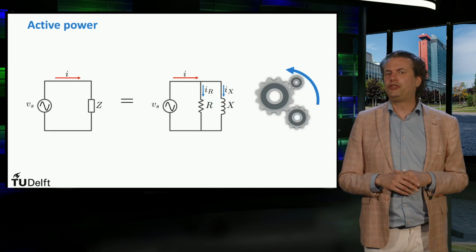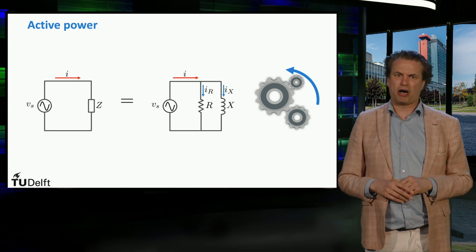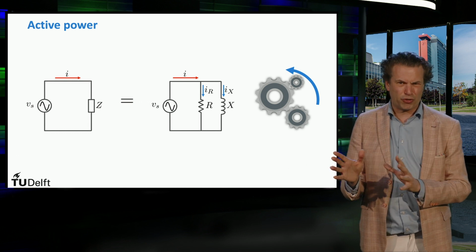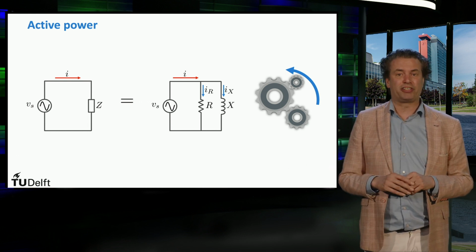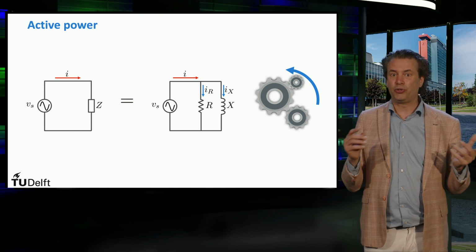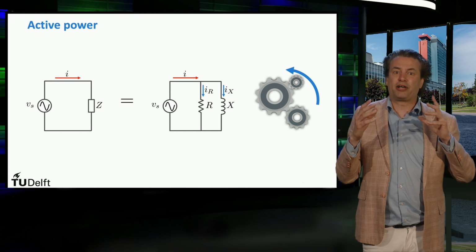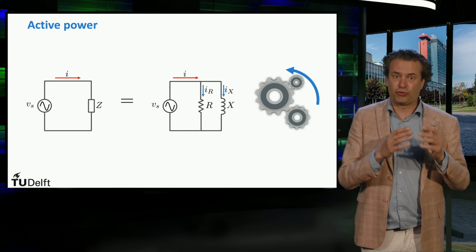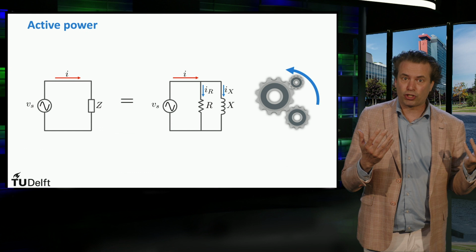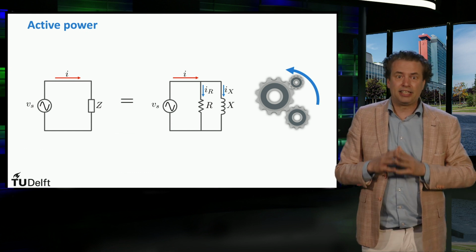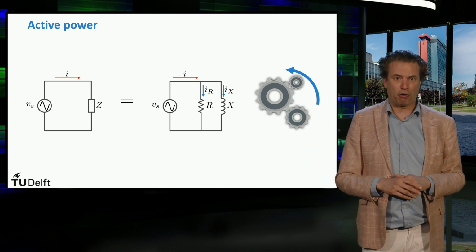Active power is the usable power. It's the portion of power that produces a net transfer of energy in one direction every cycle. The load is able to use this power to do work. In DC, the power supplied by the load is the same power that is transferred towards the load when no losses are assumed. In AC, this is just a portion of the total power per cycle.